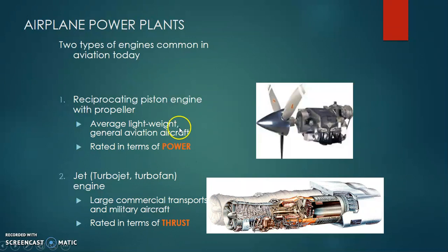The power applications are more suitable when you have smaller velocity, smaller thrust requirement operations, whereas the jet and the turbofans are more suitable for handling higher velocities, simply because at extremely high velocities up to Mach 0.8, 0.9, these engines are not proven to be extremely rugged, and the failure modes in structures coupling with aerodynamics go up substantially compared to this closed and simple intake based turbofan or turbojet engines.